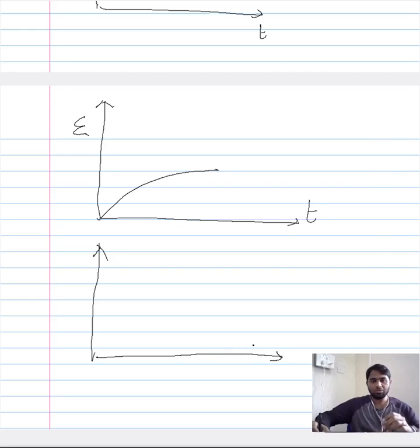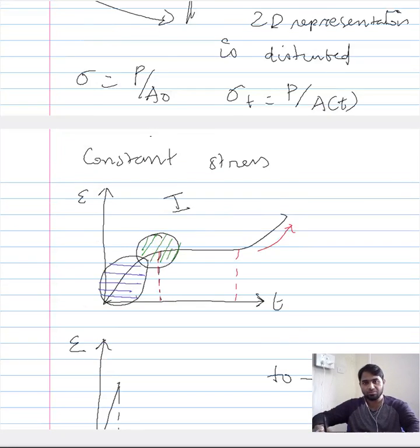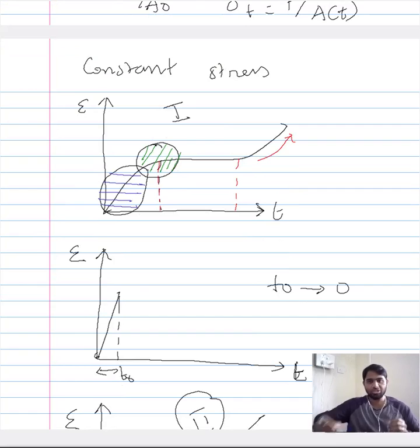Even though this gradual decrease in the slope of the strain curve occupies a very small area in the overall creep curve, it is not insignificant, because it leads to another characteristic region of the creep curve. So you have two characteristic regions in the creep curve.